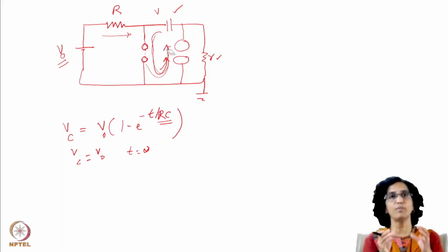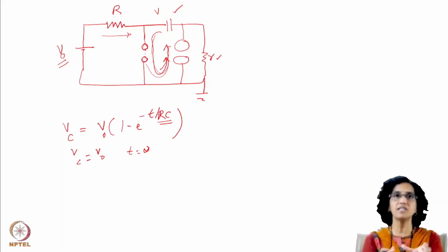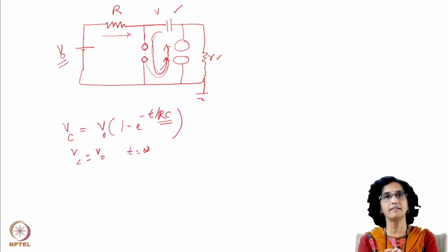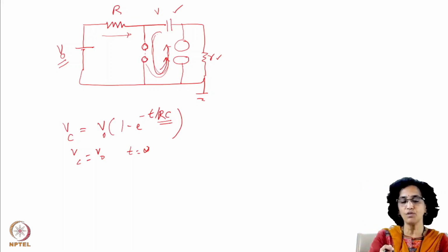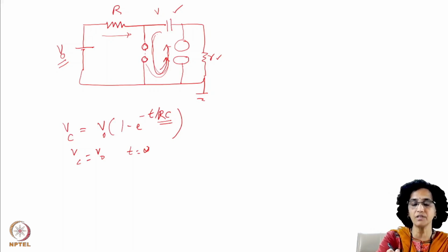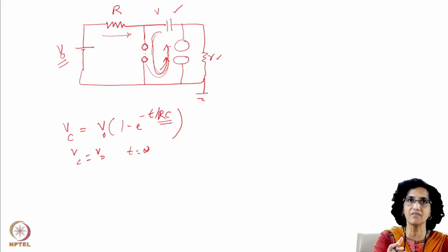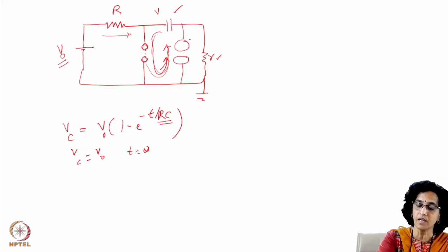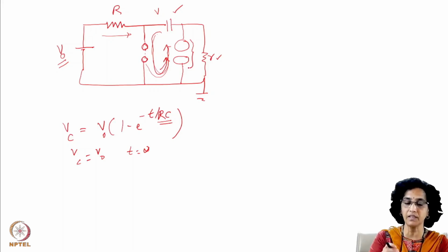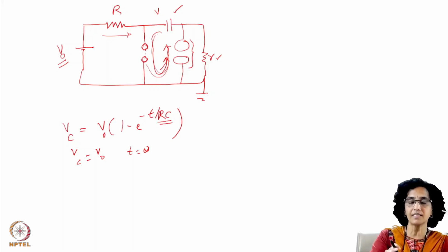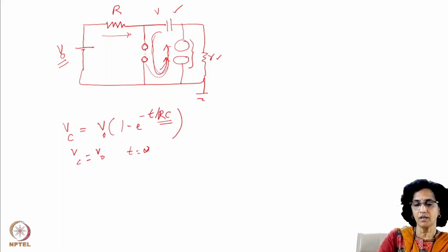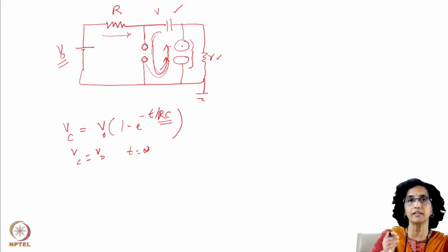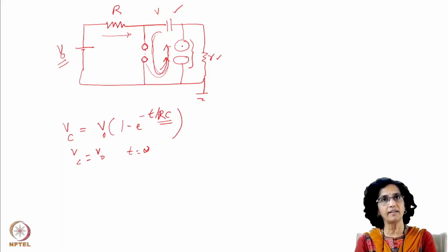So the impedance of the circuit has to be properly adjusted so that your discharge duration is less than the glow to arc transition time, which is a few hundreds of nanoseconds at atmospheric pressure. So we see that our capacitance value, the associated inductance, the resistance, and of course the laser load also has its own impedance, are such that our discharge duration is maintained within the glow to arc transition time. Now, once the condenser discharges into the load, the gas mixture in the interelectrode volume gets energized.